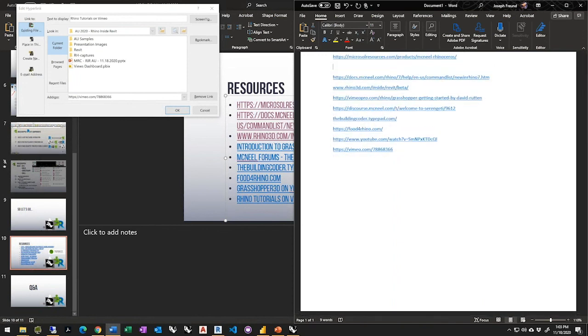Native elements, they don't care about the geometry. They care about the metadata. So Revit wants to know what's the structure of the wall, the properties of the wall, so it can generate the geometry for you. Rhino.Inside.Revit will provide you components that you work with these native Revit elements. So you can create native Revit elements, and after the creation is done, as far as Revit cares, there's no difference between that element being created manually or from Rhino.Inside.Revit or from any other Revit add-on. So you have full editing capabilities of Revit at your hand with this kind of elements.